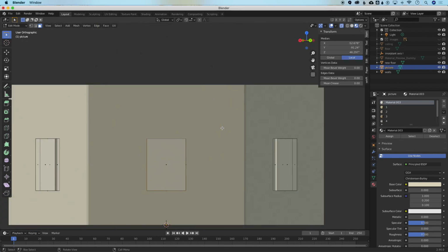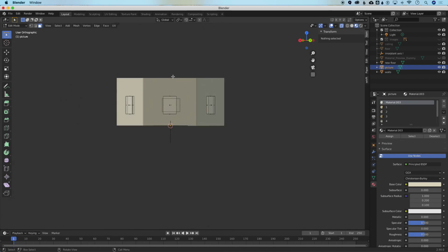I've chosen active left. Sometimes, depending on where your image is in the space, it can be tricky, and you just have to do trying, align to active left, align to active right, until you're looking straight on it. And now you can see free rotate will just rotate this right along its axis. And I'll just hit 90, and there we are.